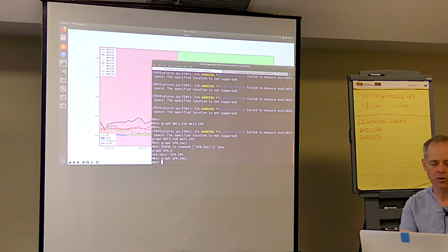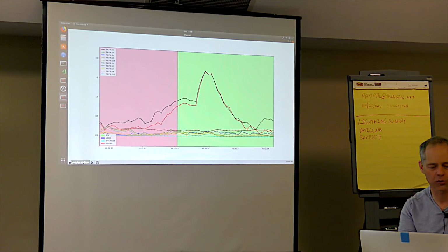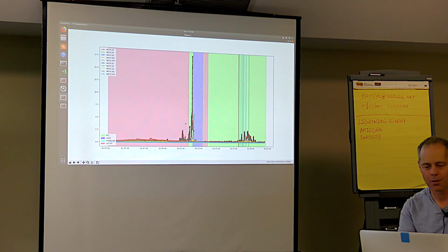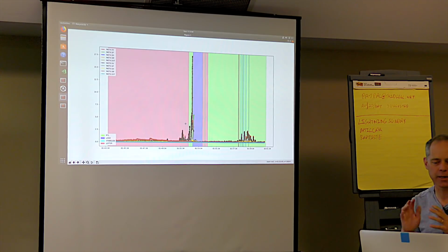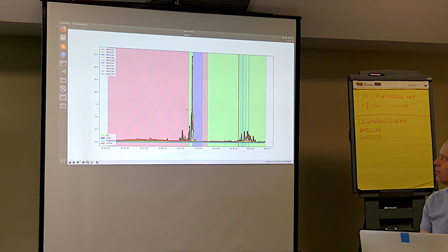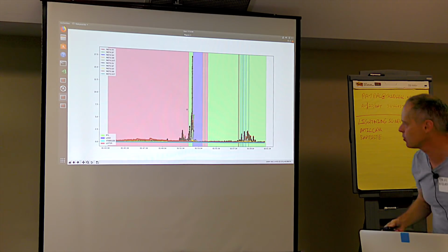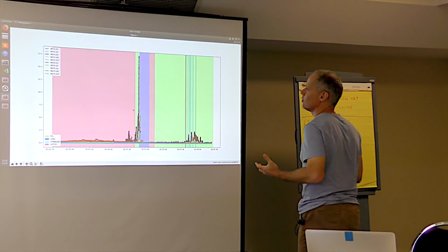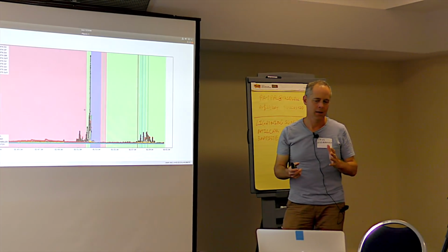Now, something else that can cause loss of horizontal position, and typically it can be either a GPS glitch, the other contributing factor, which is quite common, is the magnetometer. And I'll explain why the magnetometer matters. Why is your angle important?